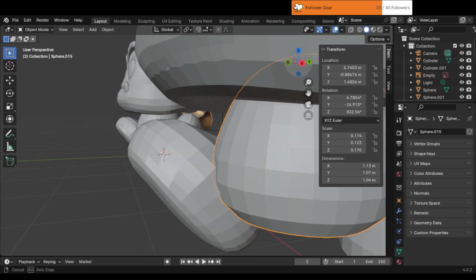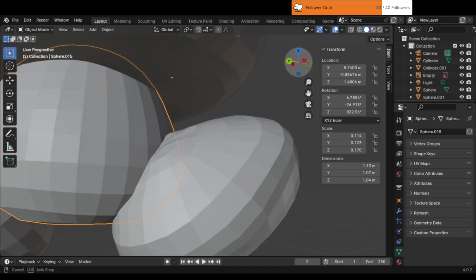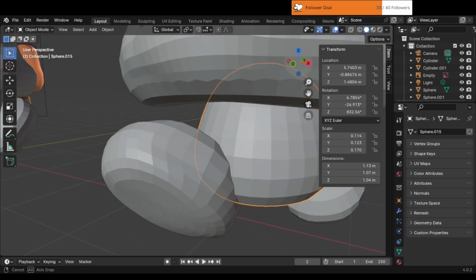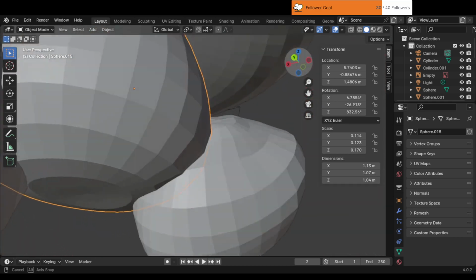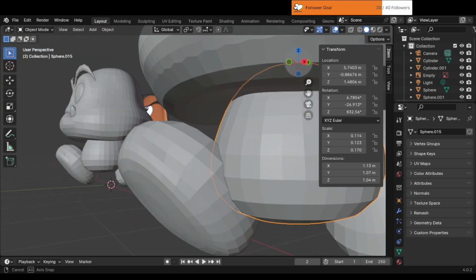Step 1. Preparation. 1. Check geometry. Inspect all models. Ensure each model you are using, both the primary model and the items for Boolean operations, is a clean manifold mesh with no holes, non-manifold geometry, or inverted normals. This will help prevent Boolean issues.